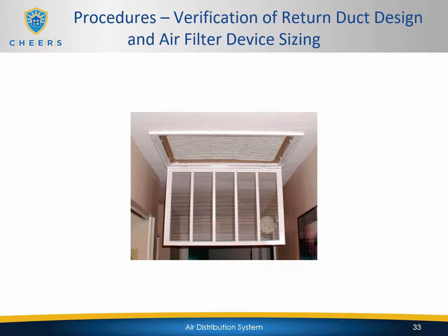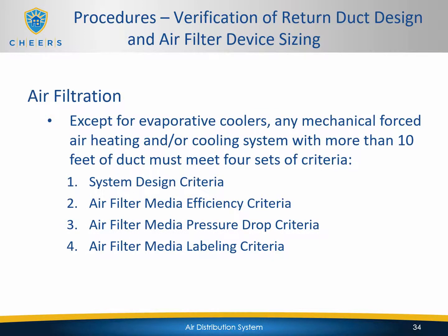The verification of return duct design is also part of HERS inspections. So for air filtration, except for evaporative coolers, any mechanical forced air heating and or cooling system with more than 10 feet of duct must meet 4 sets of criteria: the system design criteria, the air filter media efficiency criteria, the air filter media pressure drop criteria, and the air filter media labeling criteria.